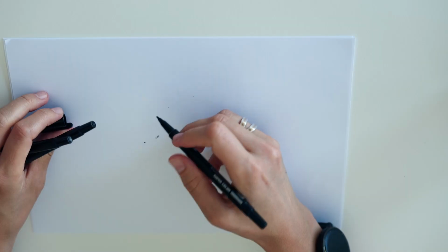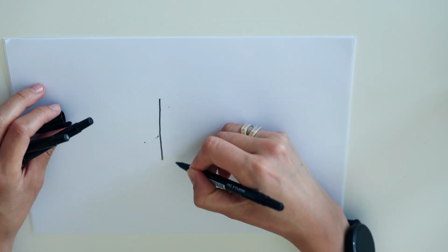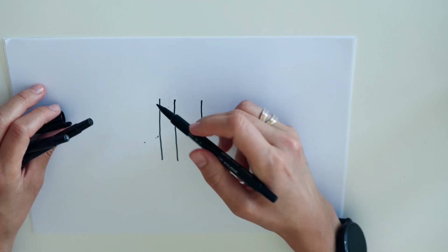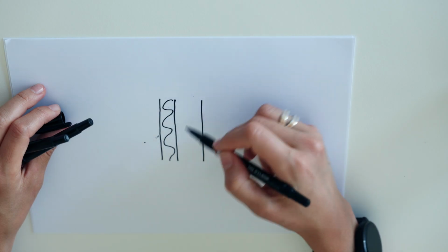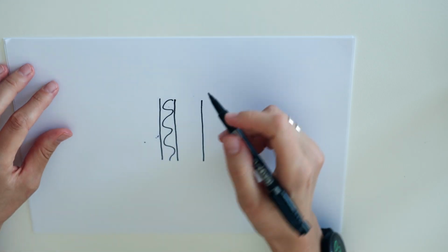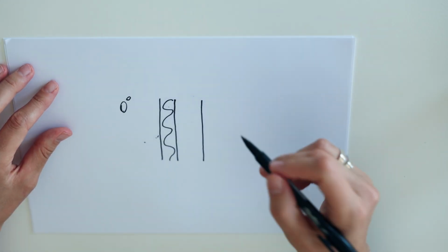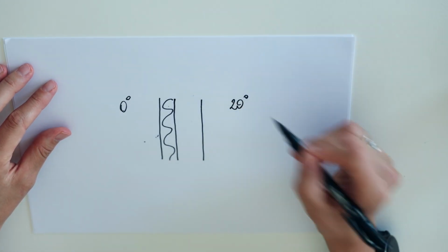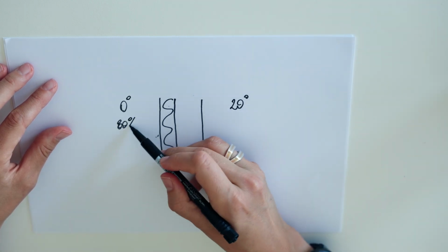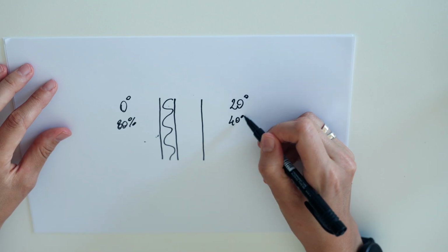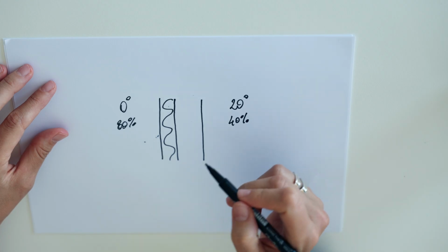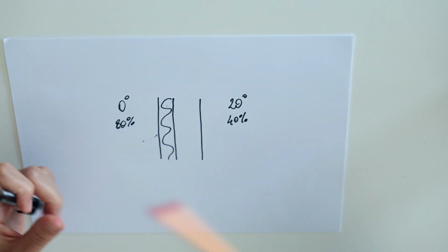methodology. A typical solid construction with an external insulation layer. So this is the insulation, this is the brick wall. So if we imagine it's winter, so outside it's 0 degrees and inside is 20 degrees, and we have a relative humidity of 80% outside and 40% inside, we are able to also define 2 things. First of all, the temperature progression.